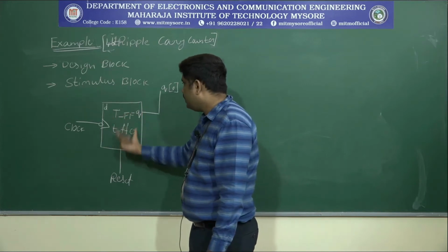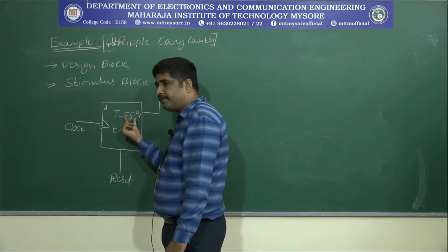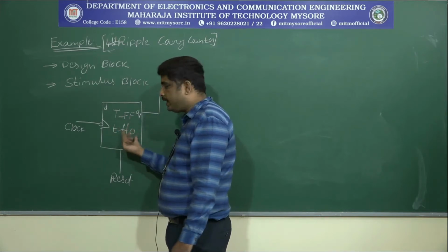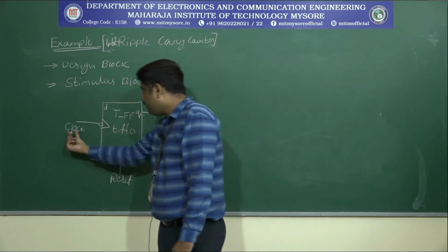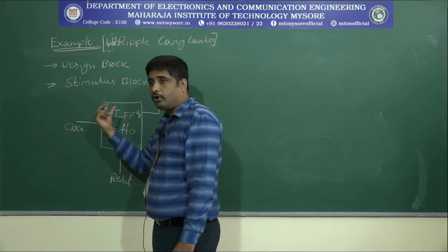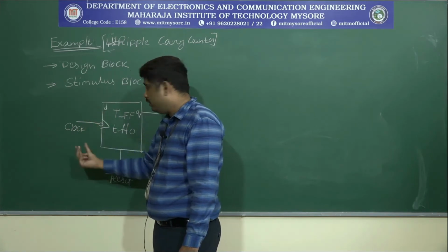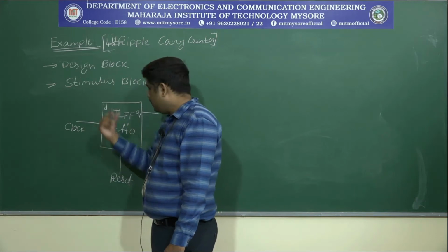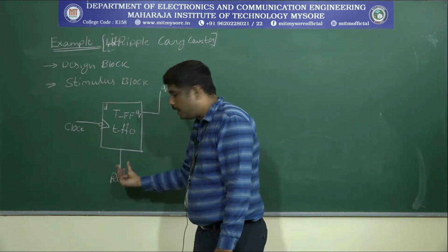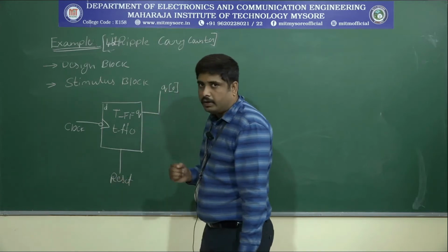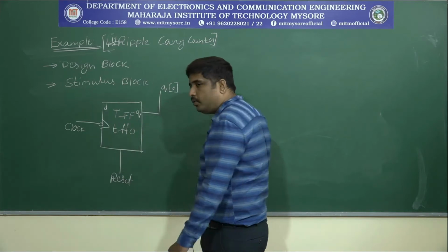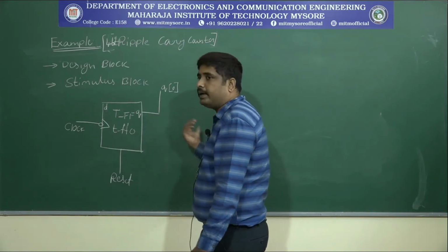The T flip-flop is named T underscore FF, then the subname is T underscore FF underscore 0. It indicates the first flip-flop. Here we have to apply a negative clock pulse, negative edge triggering. Just observe the bubble, it indicates an inverter. Next we have to apply the reset, another input, then we get Q0. Here it acts as a 1-bit counter. You just connect another one to it, then it becomes a 2-bit counter.